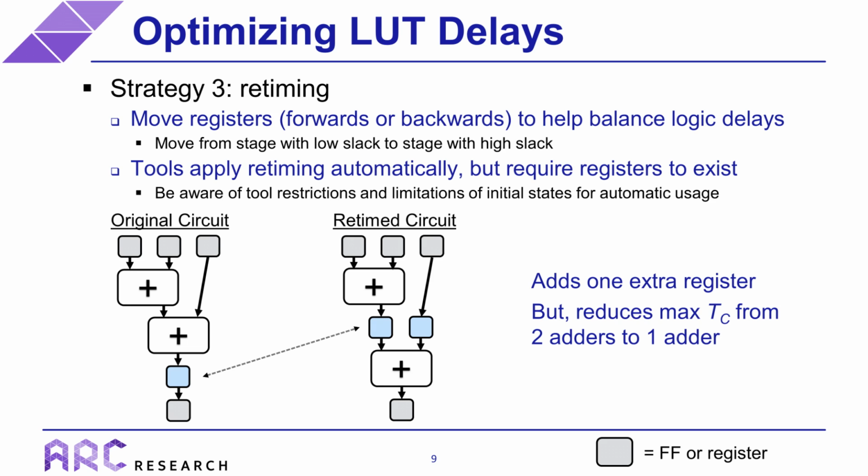Now, before you start thinking that automatic retiming can solve all of your timing problems, you need to be aware of some tool restrictions. Now, it's outside the scope of this talk to explain all the details of how to use retiming, but there are situations where manual retiming will do better than automatic retiming, and vice versa.